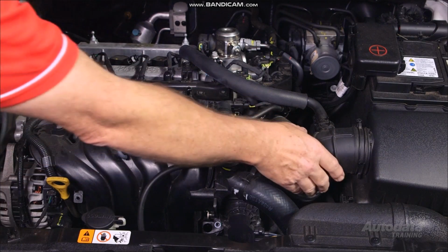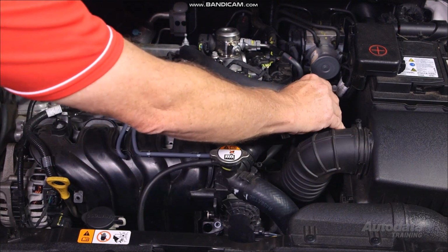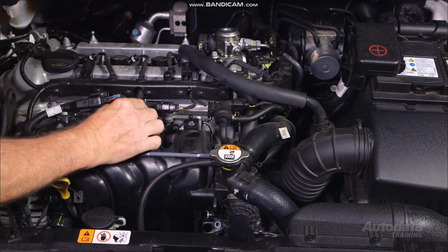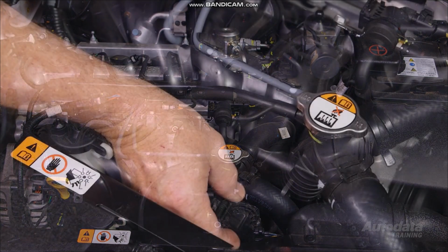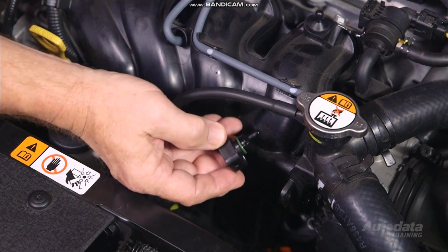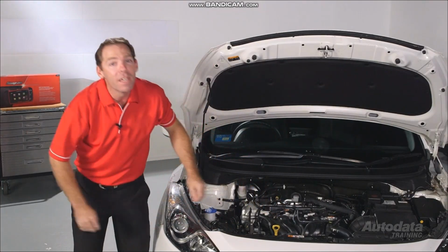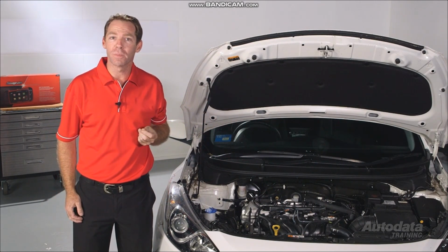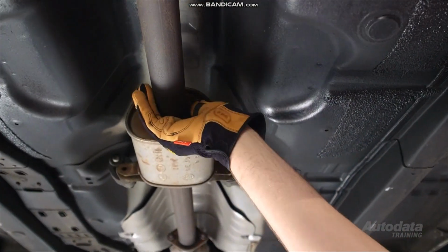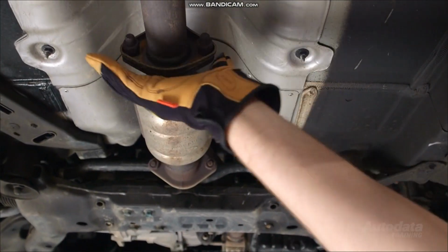It is essential that these tests and procedures be performed before proceeding to the electrical system, as concerns in these areas may cause a MAP sensor code. Check the integrity of the air induction system by inspecting for any damaged components, loose, improperly installed or routed vacuum hoses, any vacuum leaks or intake restrictions, and a missing or damaged MAP sensor seal. Ensure that the engine is mechanically sound. A compression test may be used to confirm this. Check the exhaust for any restrictions or damage.